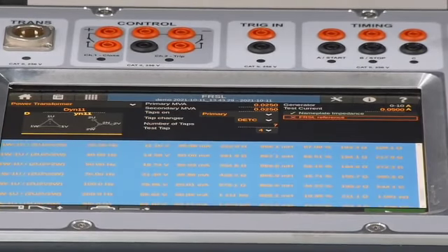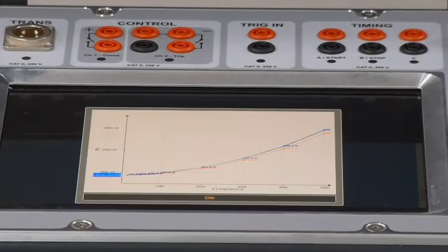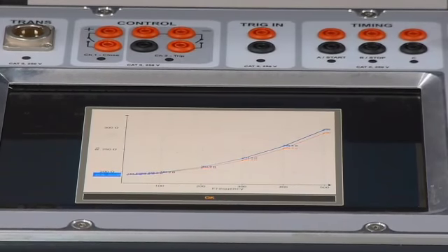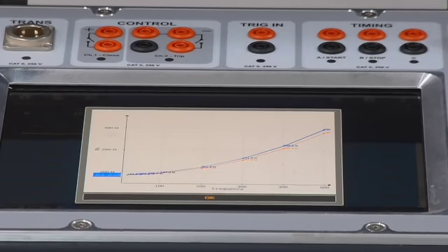So it's over now. We will go to the graph icon, and we can see now the two phases on the sides are almost identical. The mid phase is having a little bit less resistance at a very high frequency. Maybe that's a normal phenomenon for this transformer. We record this and keep it in our reference for future use, and we always compare with this result.